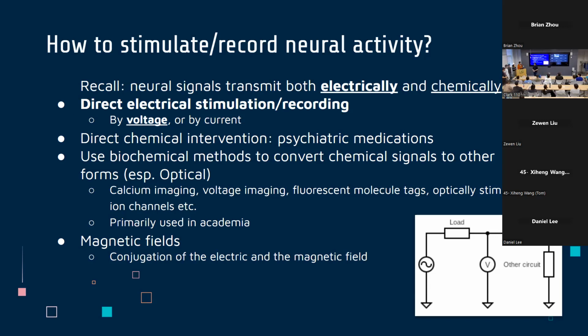So measuring voltage is relatively simple because with devices, or at least brain-computer interfaces, we usually adopt a common ground. That is, it can be somewhere that's generally signal agnostic. For example, it can be the elbow, or the base of your head, at the skull. So that is usually the common ground level, and then you can just plug the next electrode at whatever place you want to get the voltage from that place.